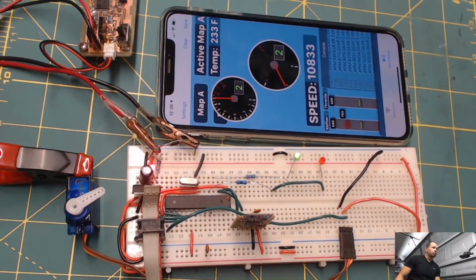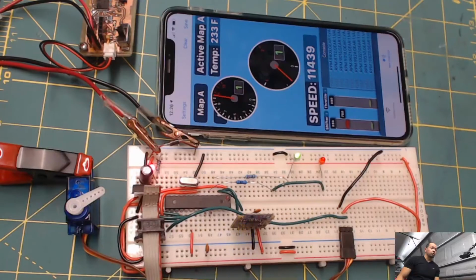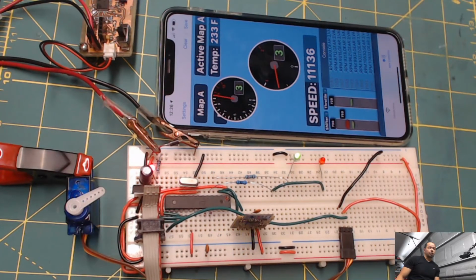We'll go through this communications file later and explain everything that it's doing. But this is pretty simple. You can pause the video if you want to see it, obviously, but let me make this code a little bit bigger so you can see it. All it is doing is checking to see if we have a message, and the message is being captured here. Whenever we get an interrupt, the character came in, we just pass that along to the communications unit or class. So we check to see if we have any message. If we do, we parse the command.